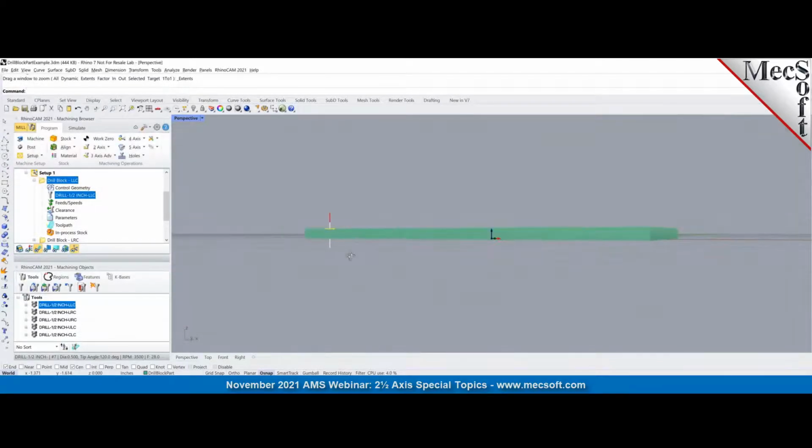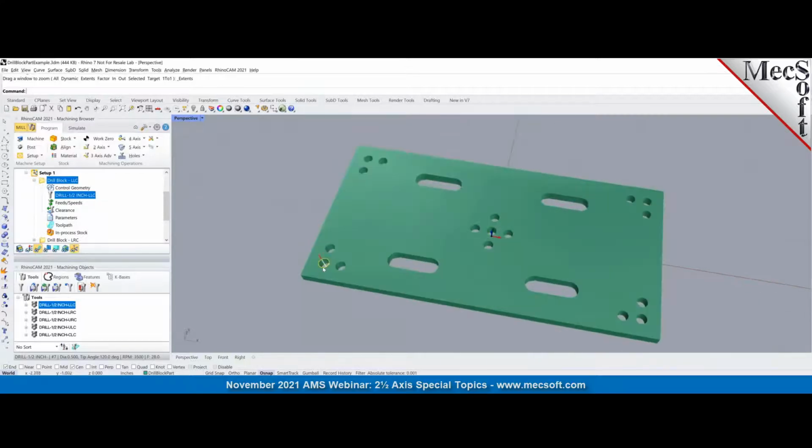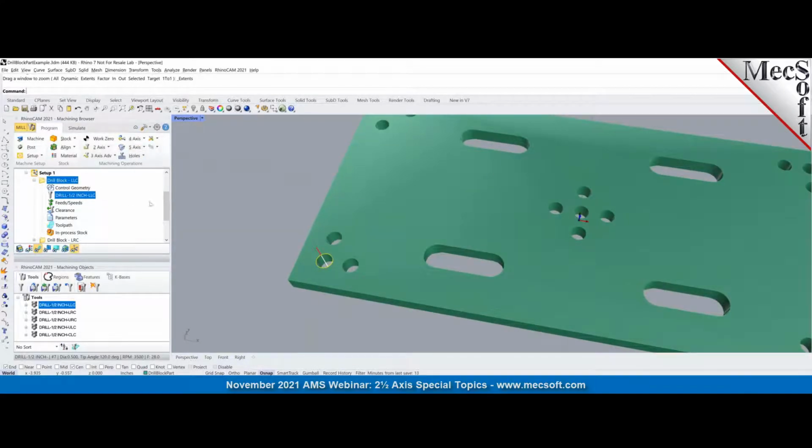So I really don't care about the depth at this point. This is just for illustration purposes. And now, even though I'm just programming the anchor bit, since I'm using the drill tool which has the binary code encoded, when I create this tool path and output it using the correct tool path post processor, it'll be decoded correctly. So let me show you that.